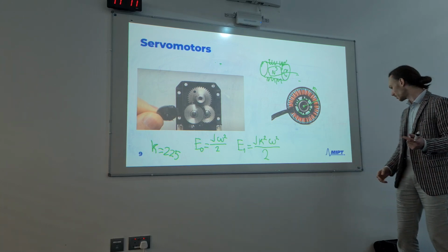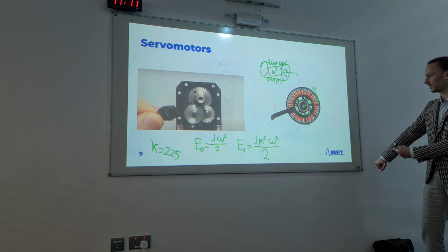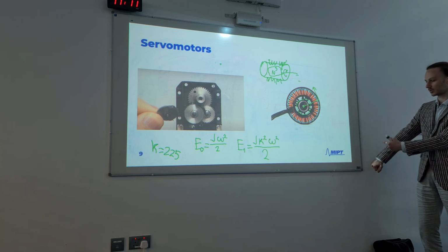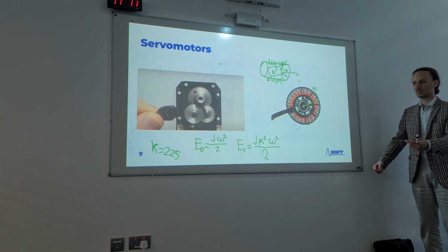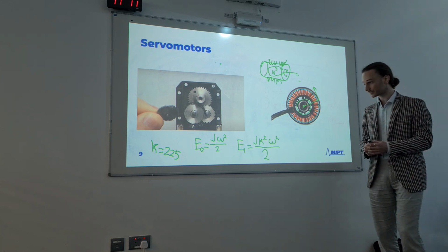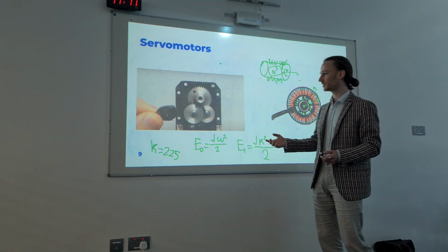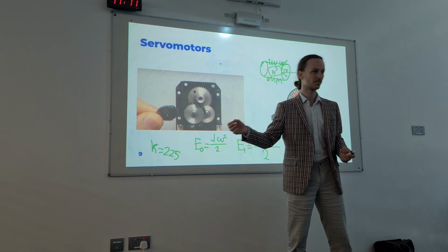So if the robot is hitting the wall, for example, with its hand, if the motor could be driven back with no power, it will be better than a very rigid motor that is not backdrivable, and that will resist this impact with all of its gearbox.